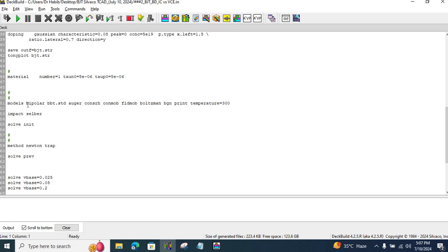It indicates the voltage at which the transistor may begin to conduct significantly high current in the reverse direction, potentially leading to damage if the voltage exceeds that limit. Therefore, collector to emitter breakdown voltage is a critical specification that engineers consider when designing circuits using bipolar junction transistors, ensuring that the transistor operates within safe voltage limits and can withstand potential reverse bias conditions without damage.